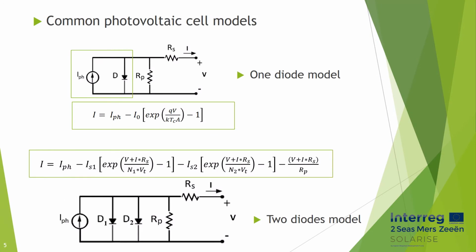Equivalent circuit of a PV cell can be simply modeled as a current source in parallel with a resistor and a diode. Those are connected in series with another resistor. The output of the current source is directly proportional with the solar radiation falling on the cell. The open circuit voltage of the cell is quite different from the cell that is connected with the load, which is shaped with RS resistor. Besides, the temperature affects the output of the cell as well.